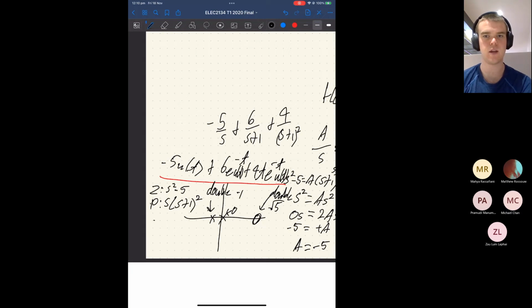Yep. Now, is the system stable? Yes, I think. Very tricky question, isn't it? Because we have these zeros here, so we're not sure. Did the zeros cause instability? You've got to remember, we only referred to the poles when we looked at stability. Since we have this pole on the 0, it's marginally stable.